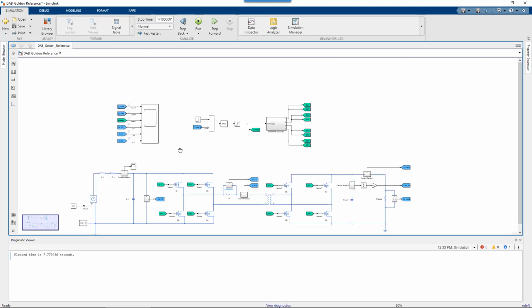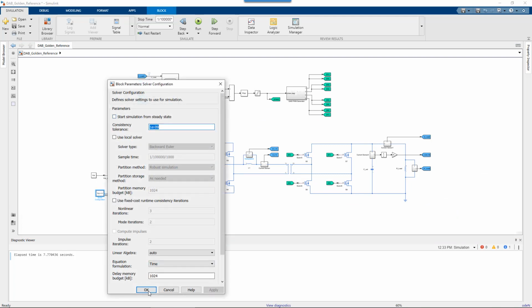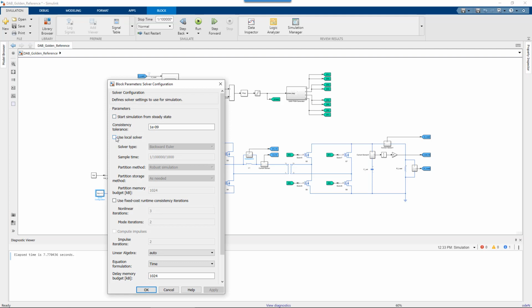Now, one final thing that you might do to speed things up is to just go fixed time step. If you ever run your model in a variable time step and it is just taking forever, and we're talking it's taking forever per cycle. It's not that you tried to simulate, you know, 1 million switching cycles and it's taking a long time. It's like, no, you're trying to simulate 10 to 100 switching cycles and it's taking forever. If that's the case, you have something we would call stiffness in the system. That stiffness might be something that you can get rid of by changing parameters, or you might be lucky and you might be able to just say, let's use a fixed step solver and step over it.